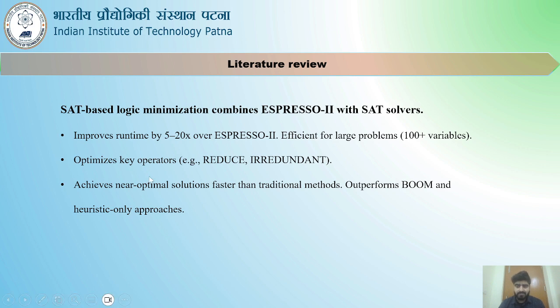So what is SAT-based minimization? In SAT-based minimization, instead of relying purely on heuristic transformation, SAT solvers analyze logical equivalence and constraints to improve minimization accuracy. SAT-based techniques speed up certain computational steps in Espresso while ensuring a more optimal solution. It optimizes the irredundant cover, reduces the previous cover, and achieves a near-optimal solution faster than traditional methods, outperforming heuristic-only approaches.